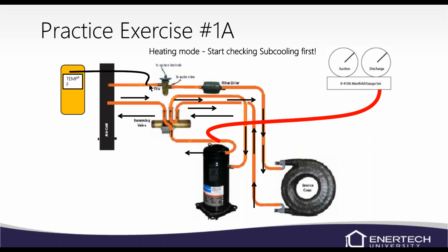If you leave the door off and you're in heating mode, then you're going to go off on high pressure because we're not getting rid of that heat into the home. We're not getting airflow across the air coil if you take the door off. We have a negative pressure coil, and so air is going to take the path of least resistance through the open door, and then we don't get airflow across the air coil. So take the door off, put your probe on there, shut the door back up.